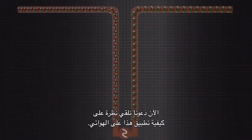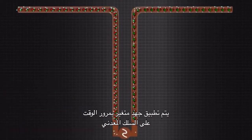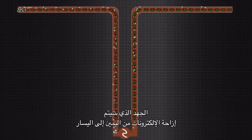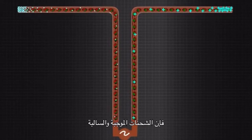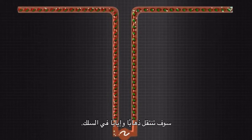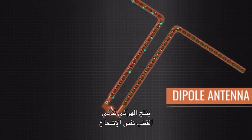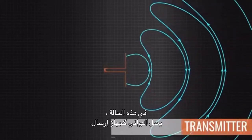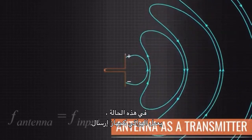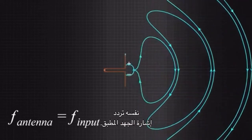Please note that this varying electric field will automatically generate a varying magnetic field perpendicular to it. Now, let's have a look at how this applies to an antenna. A time-varying voltage is applied to the metal wire as shown. Due to the effect of the voltage, the electrons will be displaced from right to left and create positive and negative charges. With a continuous variation of voltage, the positive and negative charges will shuttle back and forth in the wire. This simple arrangement is known as a dipole antenna. The dipole antenna produces the same radiation as we saw in the previous section. In this case, the antenna works as a transmitter. The frequency of the transmitted signal will be the same as the frequency of the applied voltage signal.